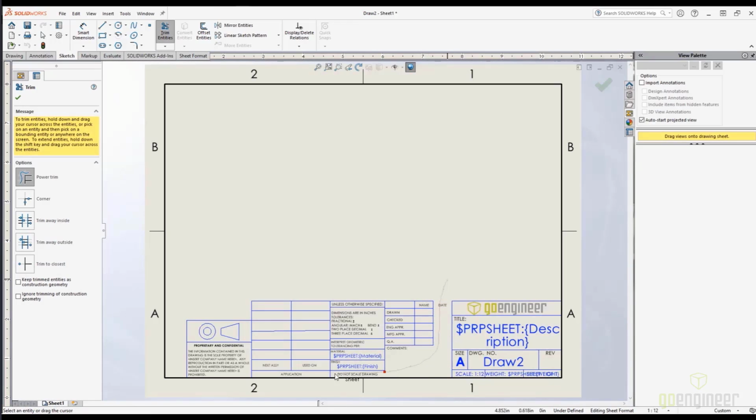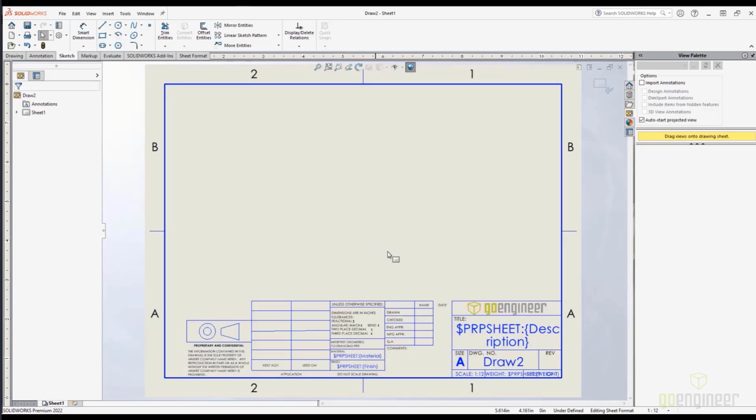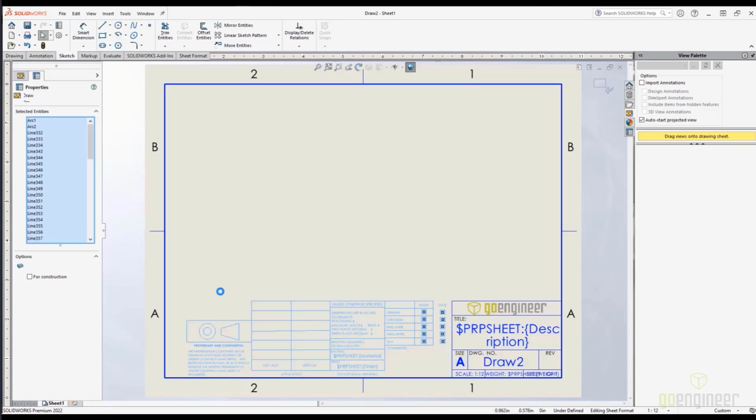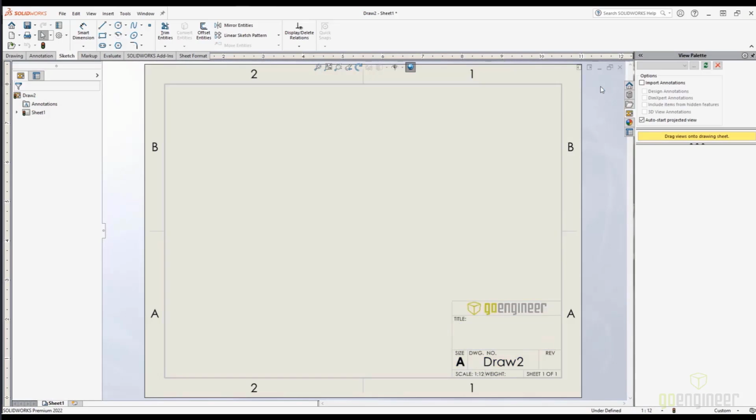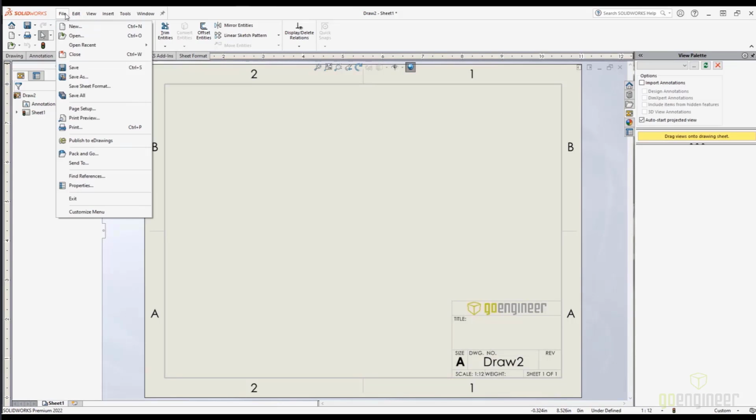because you're just starting with the first page, you can easily cut and delete what you don't need from that page. So I'm creating that second sheet format. So go ahead and edit that. So now I have my drawing down to what I want my second page or third pages to look like. I'm not going to save this as a template. I'm going to just save the sheet format. I only need to see the title block information here, so I'd click Save Sheet Format.